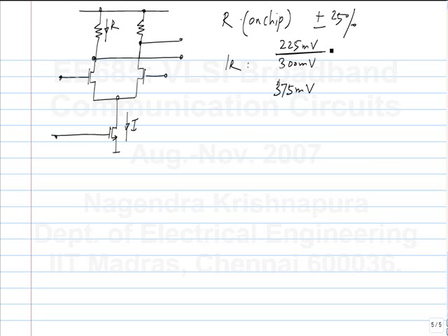So what do you do? You want to measure this voltage. Let's say for every flip-flop you measure this differential voltage and you tune the current with feedback. One thing is, of course, brute force: you make it so that for the lowest swing it will switch. But that is really a suboptimal design, because in this case it goes from 225 to 375. The lower side is a problem because the differential pair may not switch. The higher side is a problem because something may go into a triode region.